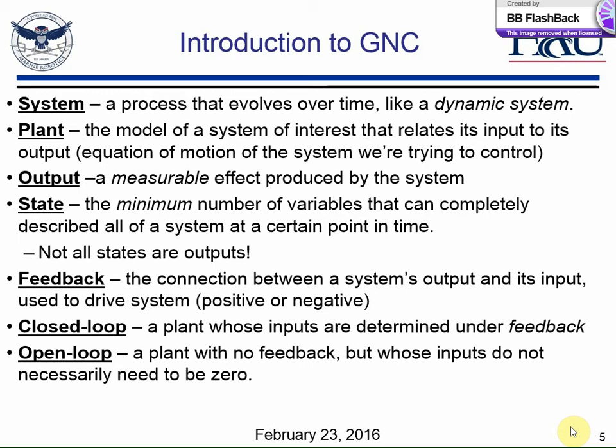With a surface vehicle, you're kind of constrained to work on a plane, right? So if we think about the table as a plane, we can only really go forward, back, left, right. Can't go down, we can't go up. We can spin around though. When we're working with a 6 degree of freedom system, it would be like us, so we're able to move up, down, left, right. And we're also able to change our orientation in 3 ways, right? So it'll be how much we roll about our x-axis, how much we pitch about our y-axis, and how much we yaw about our z-axis.